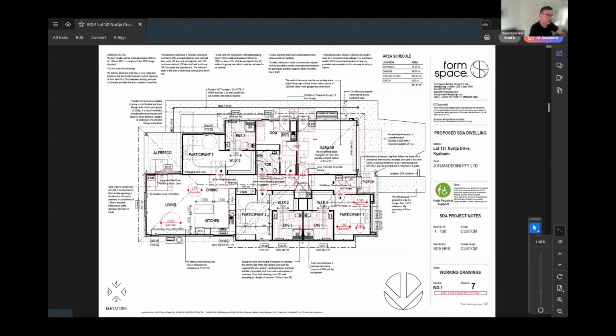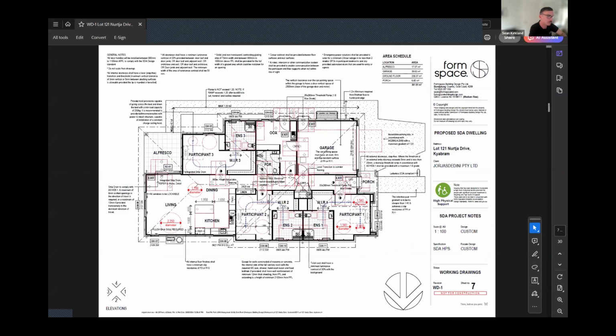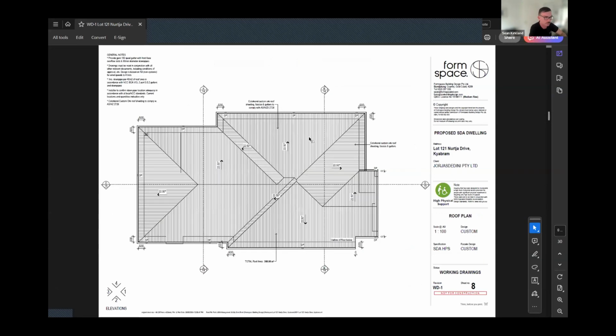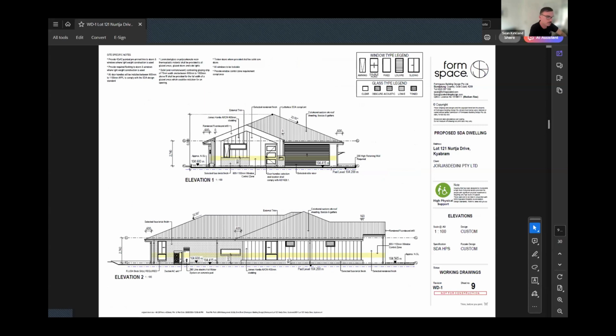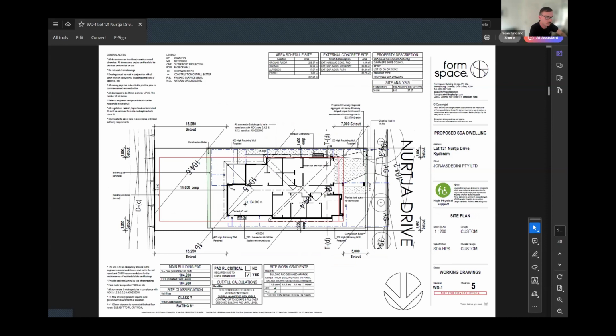So the other elements to be really mindful of, I guess, are the site slope and some of the parameters around cut and fill, and the extent in terms of zero threshold ramping, falls for the path access required into the home, etc. So there's a closer relationship in terms of the building pad to ensure that it meets across full requirements and the entry into the home.